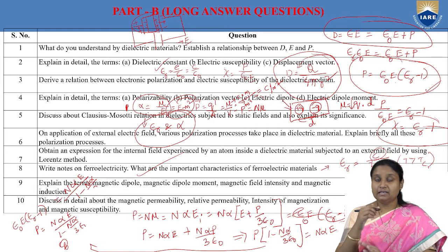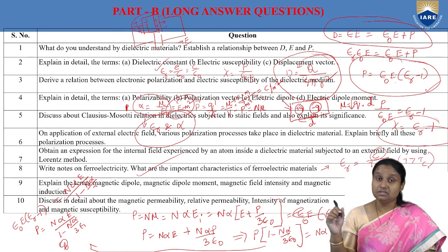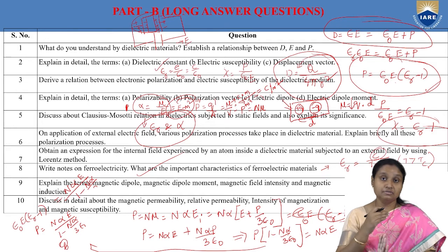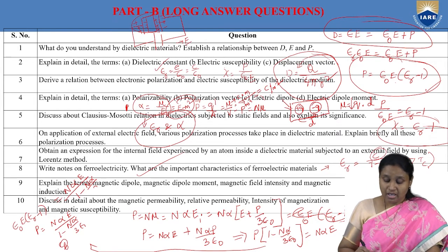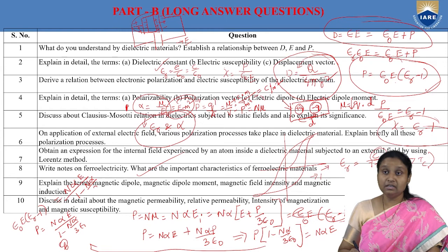What we observe here is that at Tc there is conversion of ferro to para. In the para state, the dielectric constant decreases with increase of temperature, but as long as it is in the ferro state, the dielectric constant increases with increase in temperature. And one more thing: ferroelectric materials exhibit a hysteresis loop, which is the plot taken between electric field and polarization.